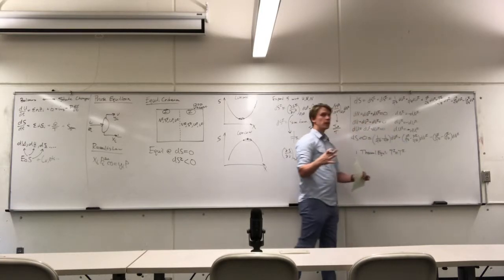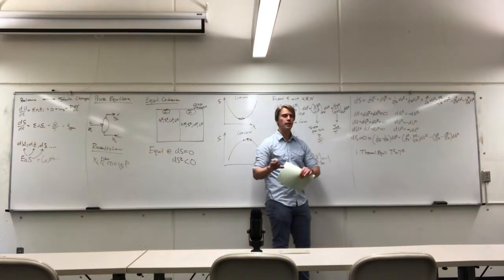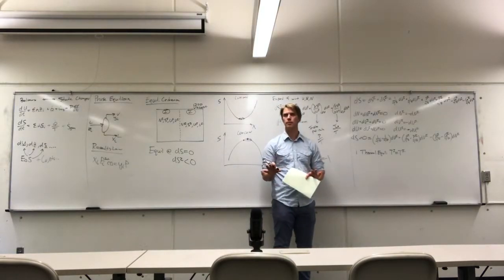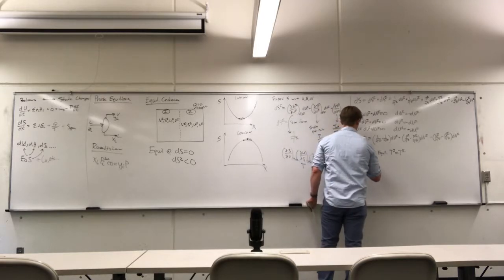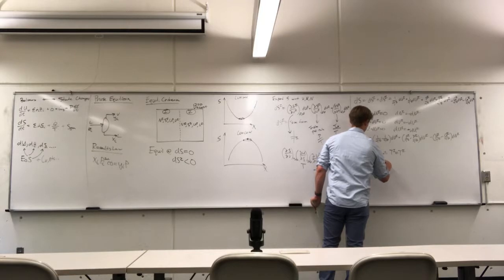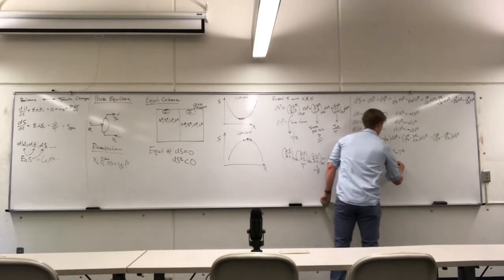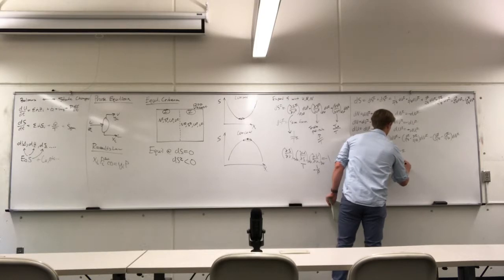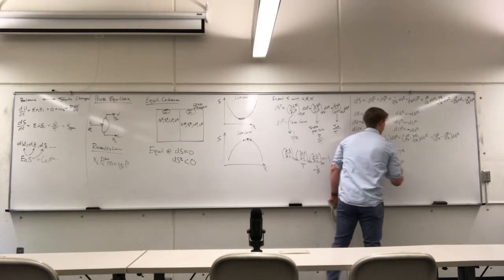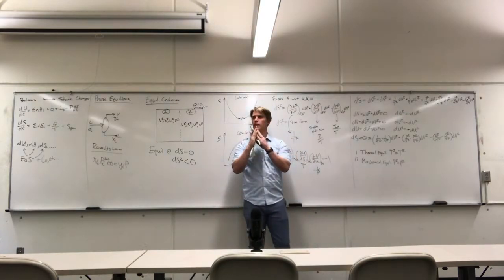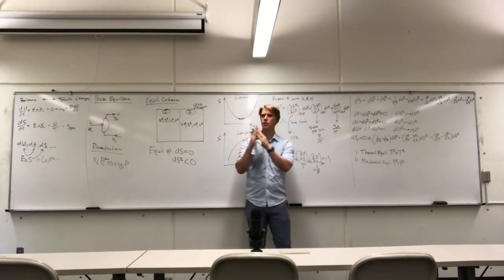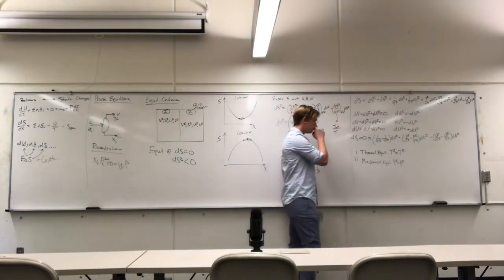Right? Not their internal energies. The internal energy doesn't have to be the same. The temperature has to be the same. Criteria 2 is mechanical equilibrium. That the pressure across both of the 2 chambers have to be in equilibrium. They have to be pushing against each other exactly the same so that the volume is not being exchanged between one system to the other.